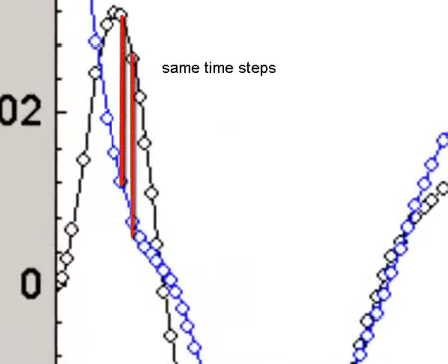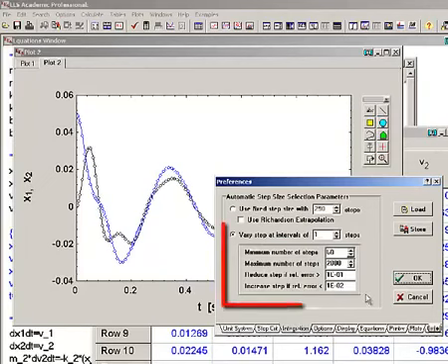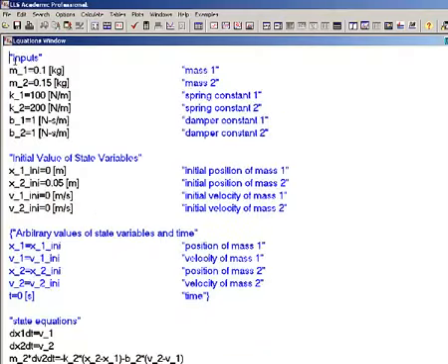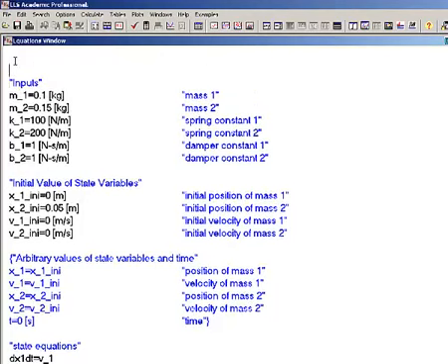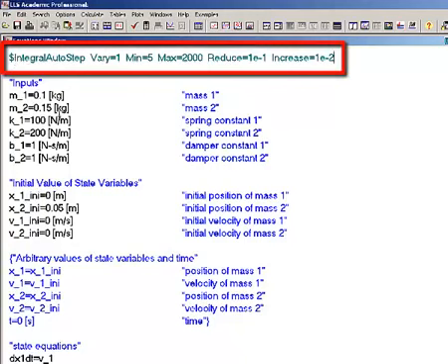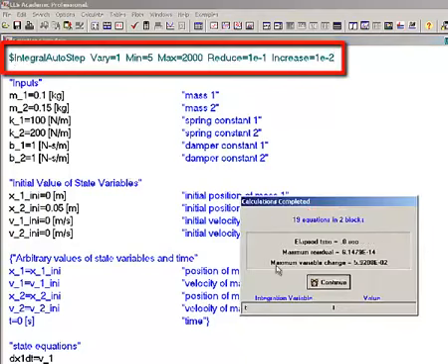The settings used for the integration can be adjusted in the Integration tab of the Preferences dialog, as shown here, but it's probably better again to use the $IntegralAutoStep directive to set the integration parameters directly in the EES equation window, which is shown here.